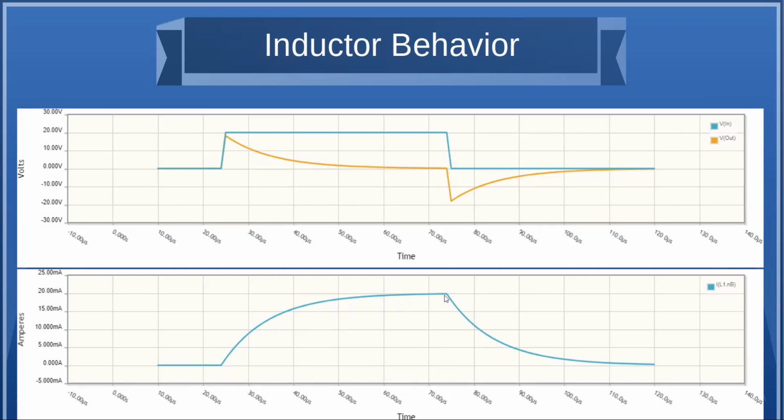And at that point, from the DC point, it looks like a short circuit. It has some very small resistance value, but it's essentially a wire. And that's why you're going to see different behavior with alternating current. Initially, it looks like an open circuit to an AC waveform.